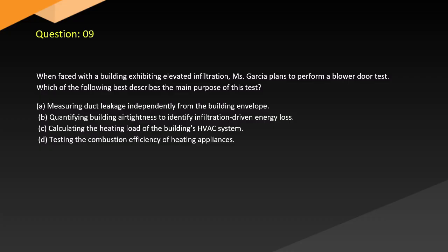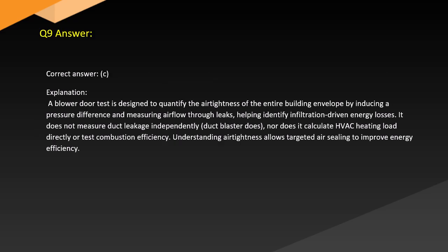C. Calculating the heating load of the building's HVAC system. D. Testing the combustion efficiency of heating appliances. Answer. Correct answer. C. Explanation. A blower-door test is designed to quantify the airtightness of the entire building envelope by inducing a pressure difference and measuring airflow through leaks, helping identify infiltration-driven energy losses.